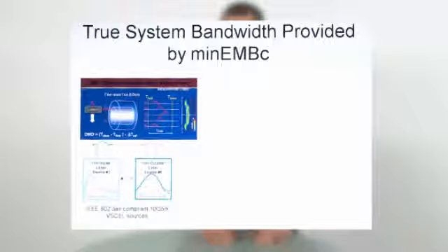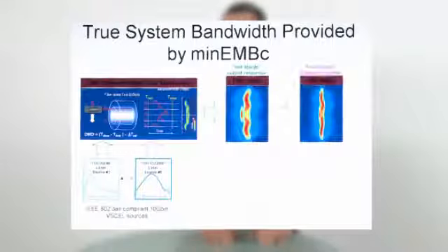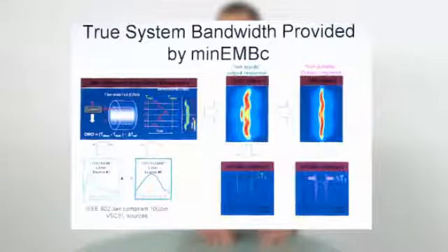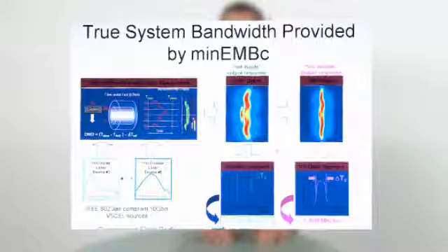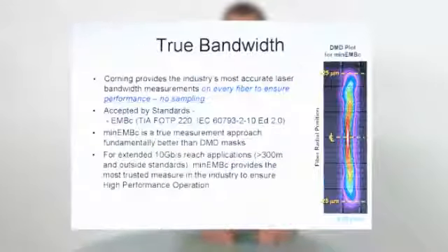Corning measures differential modal delay using several VCSEL sources, chosen to check at the extremes of the allowable laser sources. This slide shows the difference in just 2 different VCSELs. Several more results, using widely varying VCSELs, are combined to calculate the minimum modal bandwidth of this fiber using any possible standards-compliant VCSEL. This is called Calculated Minimum Effective Modal Bandwidth, or min-EMBC.